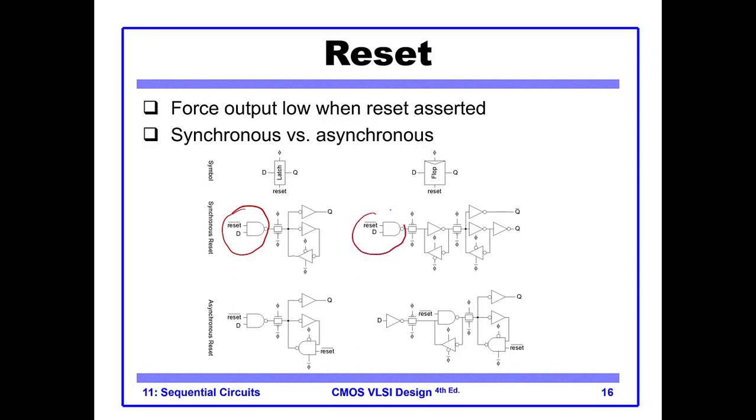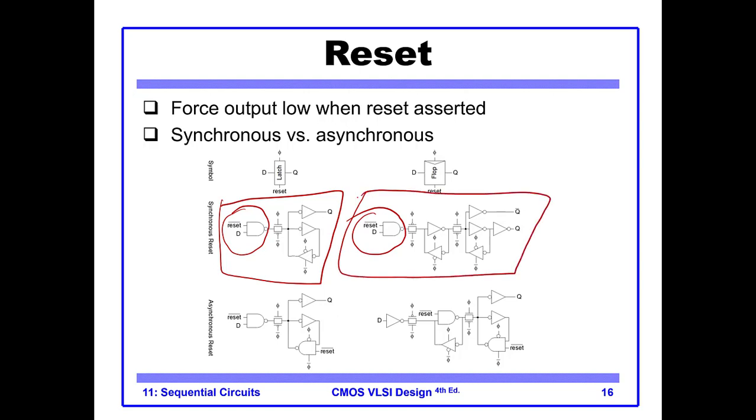So this is synchronous. This one is for a latch, and this one is for a flip-flop. And you see it is written synchronous reset. A synchronous reset is a reset which is only considered when a positive edge of clock arrives.